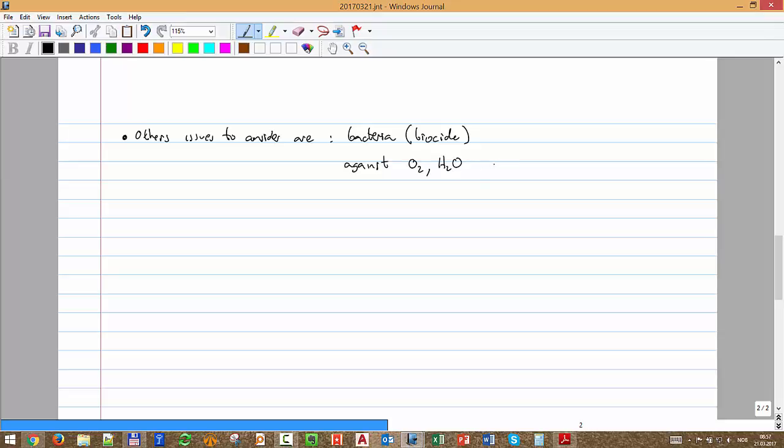So we have what we call scavengers for oxygen and H2S, sorry, it's not H2O, it's H2S, sequestration. That's to mitigate corrosion. Some other things that we have are antifoamers. That's needed when I have liquid plus gas. All of you know what foam is. That creates this kind of foam or bubbly structure, and that's very difficult to separate.